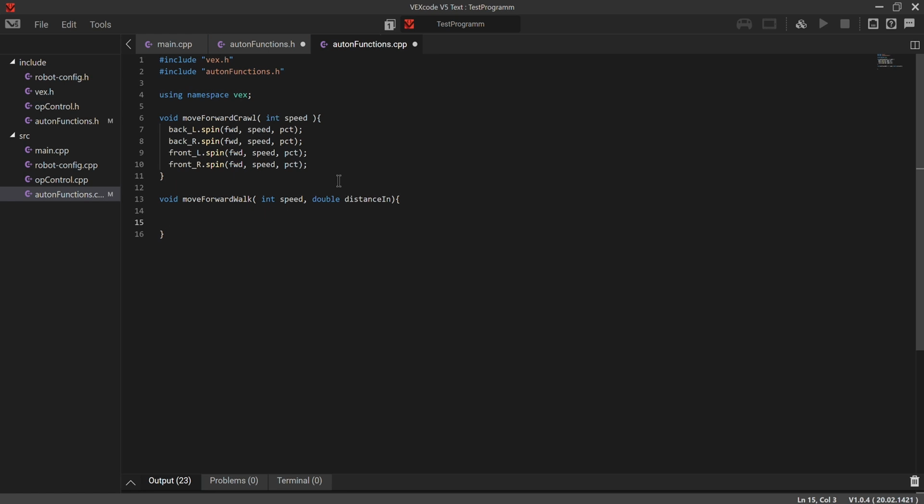So there's not going to be any human errors from code because of how complex it is. So then when we run it, we see, oh, the robot actually does go straight. So then you know that it's actually not the robot's fault, it's your code's fault. Or maybe it actually does curve in the crawl program. If it does curve in the crawl program, then you know, okay, maybe it's not my code's fault, but the way the builders built it, or there might be some friction, or maybe a motor might be dead. So that's something else you might have to figure out later, but this saves you from scratching your head and thinking, oh my god, how do I figure this out?